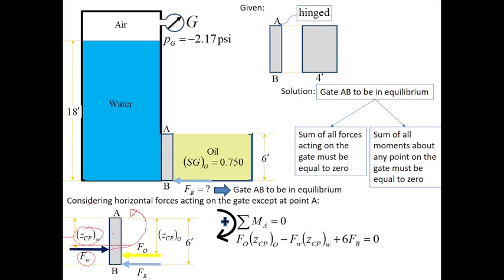And with that, the direction of the moment is counterclockwise, right? That's why it was given a negative sign, because we only consider the clockwise direction as positive. Therefore, if it is counterclockwise, it will have a negative sign.